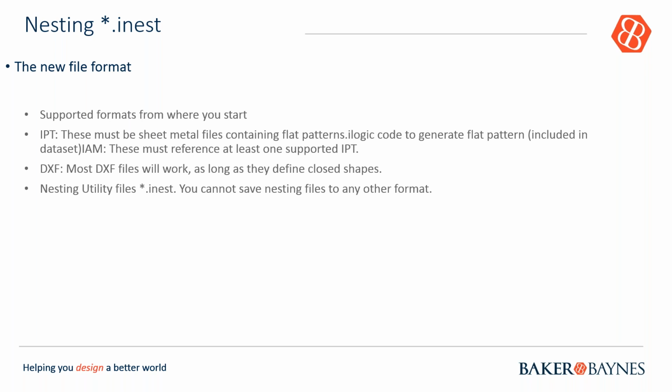Okay. DXF, if we look at DXF, most DXF files will work inside of it as long as they define a closed shape. And then the nesting utility files are .inest files, and you cannot save these files in any other format. So it needs to maintain that inest format.